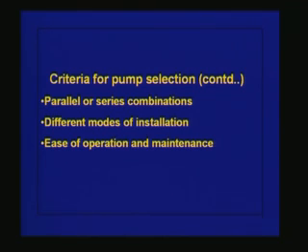Now we can do this with one single large pump which gives that very high discharge, or we can do the same operation by using 3 or 4 more pumps which are used in parallel, so that the head, the lift given by all these individual pumps is the same, but when you add the discharge from each of these pumps, the total discharge meets our demand.